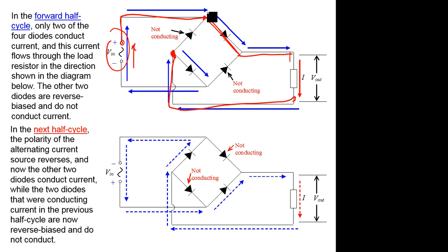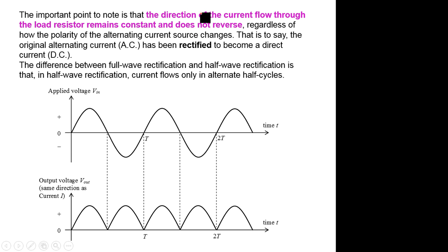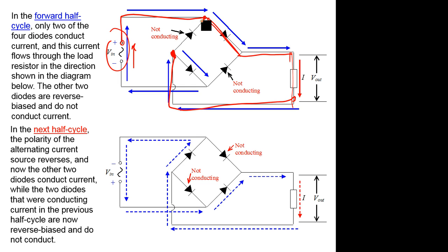That's right, because you have already moved through a resistor. You have moved through a resistor, so the potential at this point, at the top, must be higher than the potential here. The current only moves to a lower potential. So it has no choice but to move down, come back, complete the circuit. Okay, so I'll erase all this first. But the point is, the current through the resistor on the output side is downwards. This is the key takeaway.